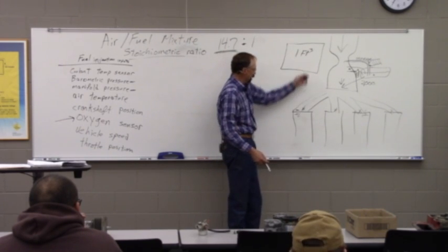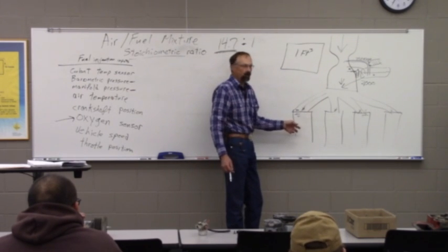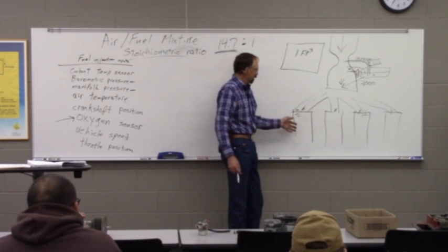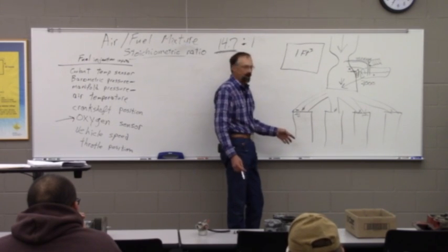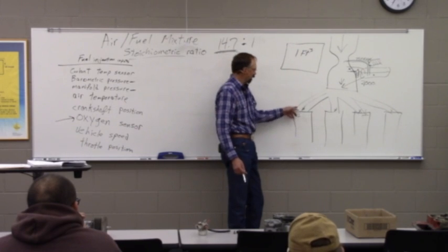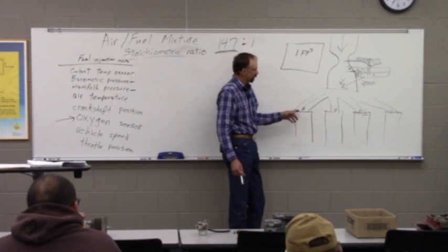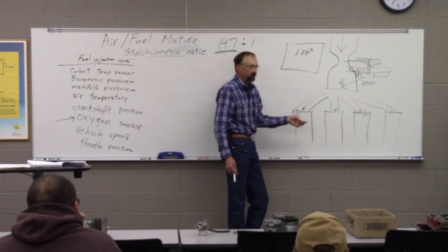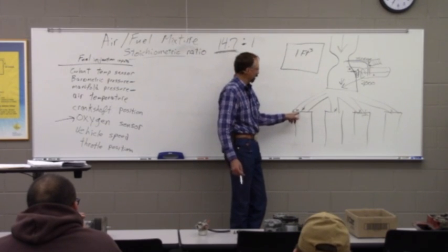And then the valve opens and we got a suck of air and it'll suck that all in, but some of it may have puddled and may still be more liquid than vapor. We're talking minuscule amounts here, but at the same time, when we're trying to get best efficiency, we want all that to be vaporized. And so there again, the fuel mileage was helped, as well as the emissions were helped when they went to the sequential multi-port fuel injection.